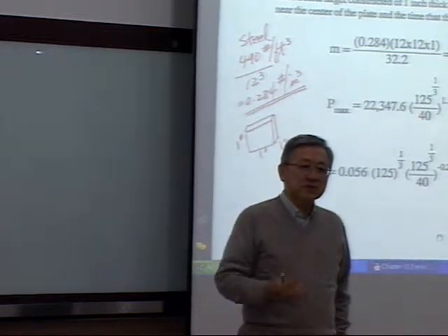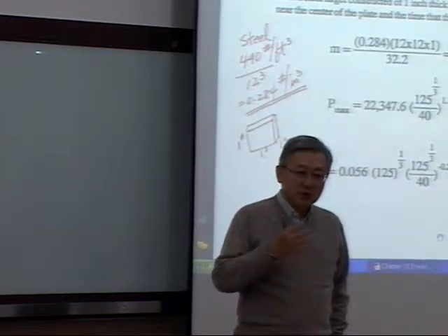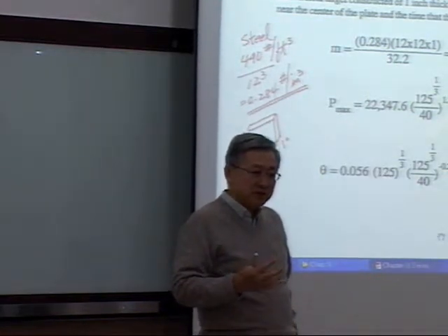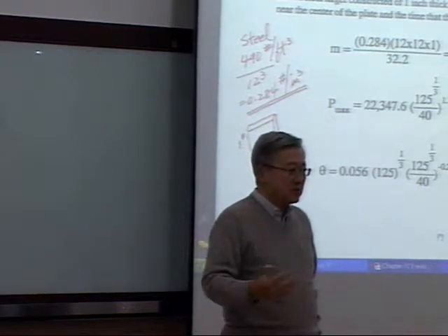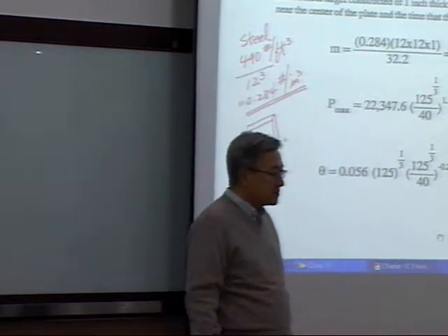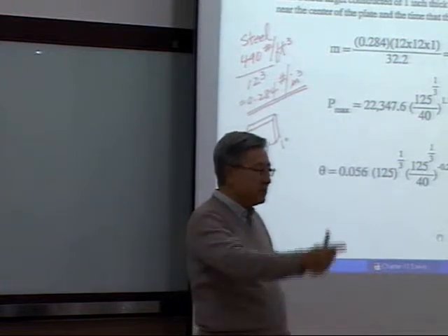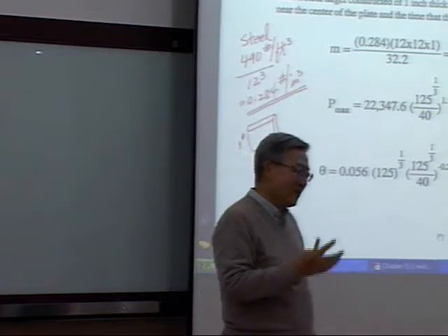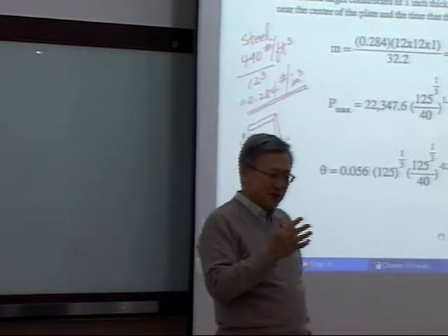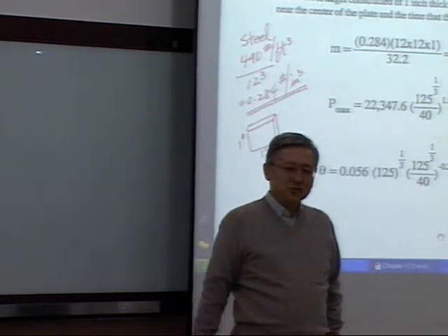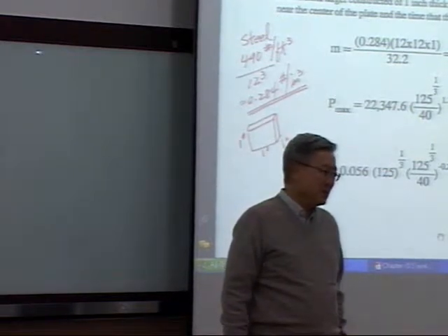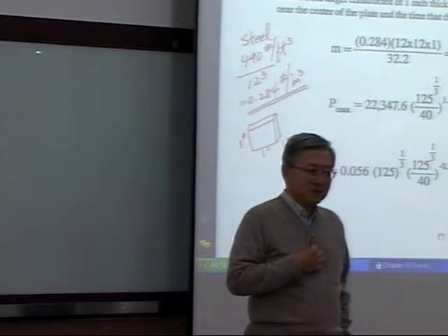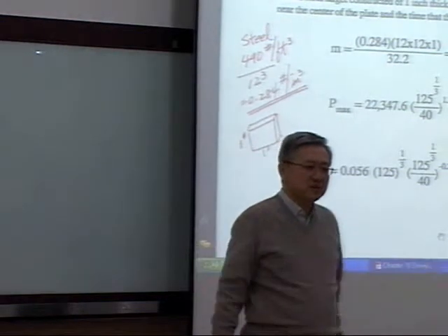For example, for the valve, or you can say penetrator or penetration, which takes seawater in and seawater out, you have to have a proper weld. Why? If you feel, oh, this weld should be good enough. No. Doing the shock testing, what I observed was it just busted out.